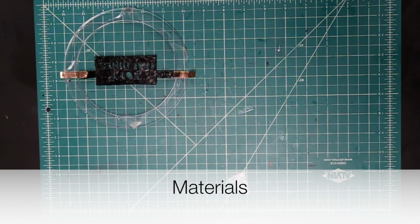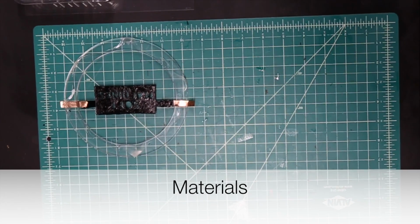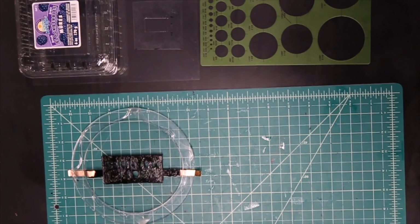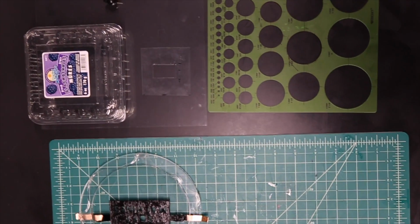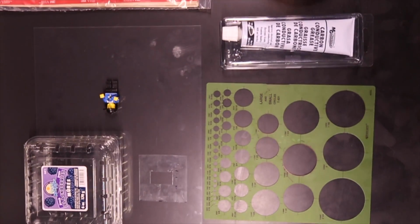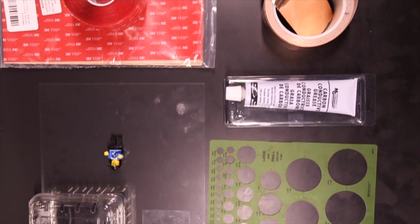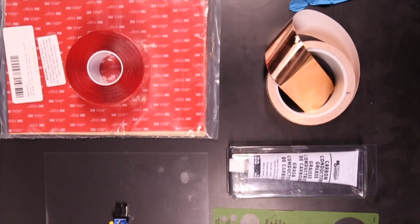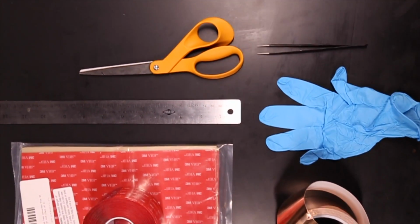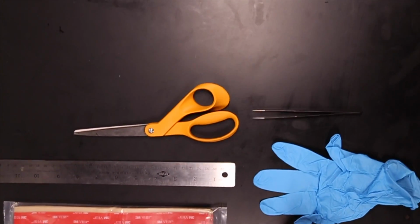Here are some of the things that you may need in order to make your own DEAs. First, you need a cutting board to cut these plastics in precise shapes. This can also be done in a laser cutter for more precision. You may also need a thin plastic sheet. Now, this can be recycled from a strawberry package or any other plastic package you may find. As stated before, you will also need carbon grease, gloves to avoid spreading the carbon grease, and copper tape as an interlay between the carbon grease and the power source, in this case an alligator clip.